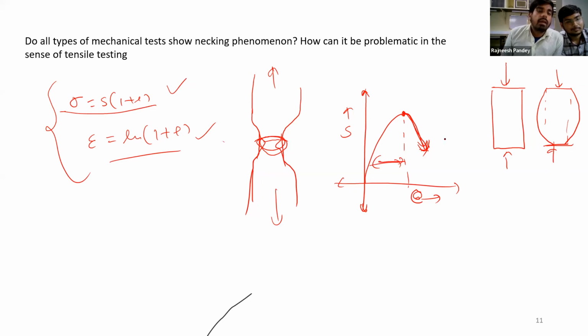So what happens when necking occurs? All the stresses acting after the UTS are localized in a narrower region, so there is no significant amount of elongation, but radial direction deformation is still taking place, meaning the cross-sectional area decreases much more rapidly.